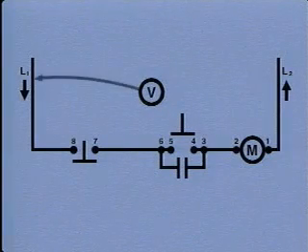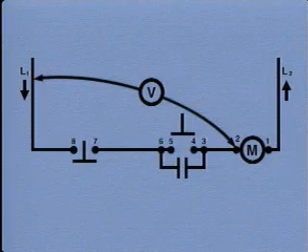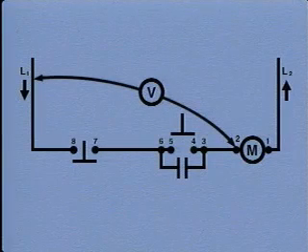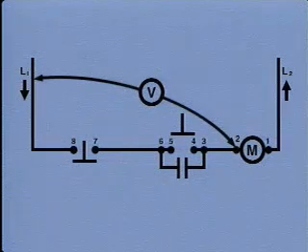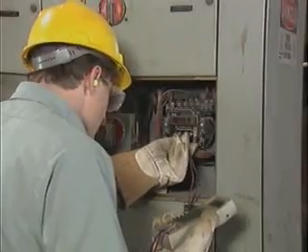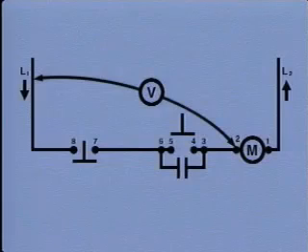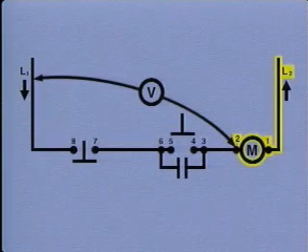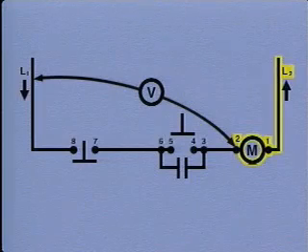The next step is to place one of the probes on L1 and the other on electrical connection point 2. If the circuit from L2 through the M coil is complete, voltage will reach connection point 2, and the voltage tester will indicate full line voltage. When the electrician conducts the test, the voltage tester gives a full line voltage reading. Voltage is reaching connection point 2, so the M coil and the wiring from the M coil to L2 are good. The power supply, the M coil, and the wiring from the M coil to L2 can be eliminated as the cause of the problem.